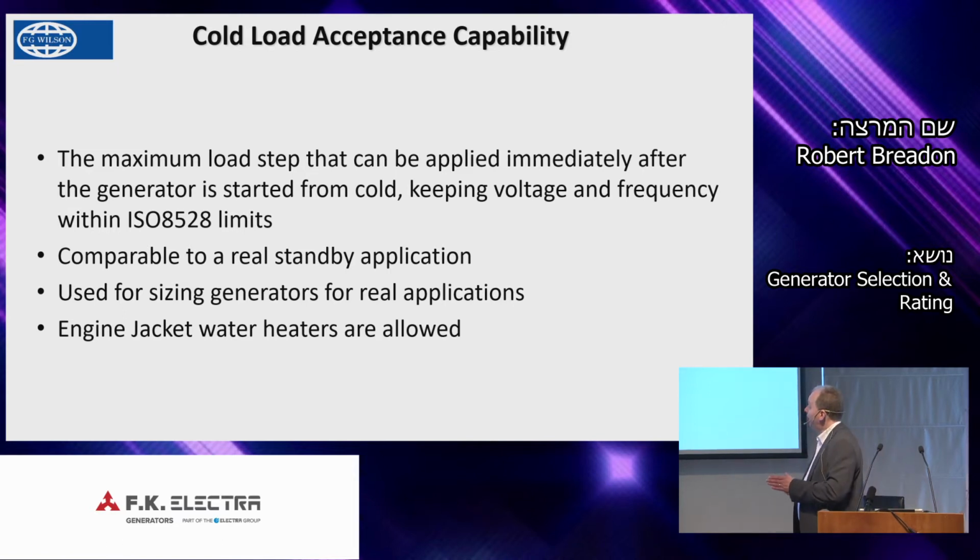In this particular case, you're allowed jacket water heaters to be on overnight for this test. In the other test, the engine was run up on full load and taken up to working temperature before any of that testing was carried out.